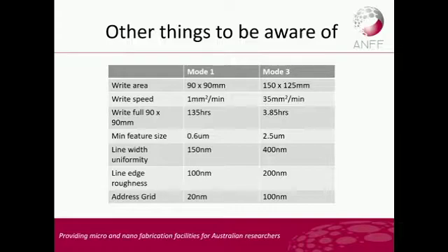So also just mention the address grid. When you are doing your design, you can also set up the manufacturing grid. So that's the grid that's used within your design. I think by default it might be set to 1 micron, I'm not sure. So if you're drawing circles, you need to make sure you use a suitably small manufacturing grid. And we can show you all these things when you actually come to do the software, and we can train you up on how to do the software.